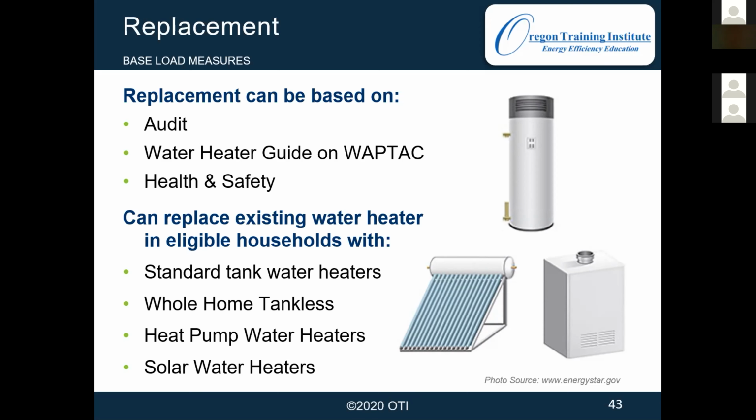But there's also tankless water heaters. I'd stay away from electric tankless because they're not very efficient, but gas, since gas is so much cheaper than electricity, they can be worthwhile. And tankless water heaters, the way that they save energy is they don't have standby loss.